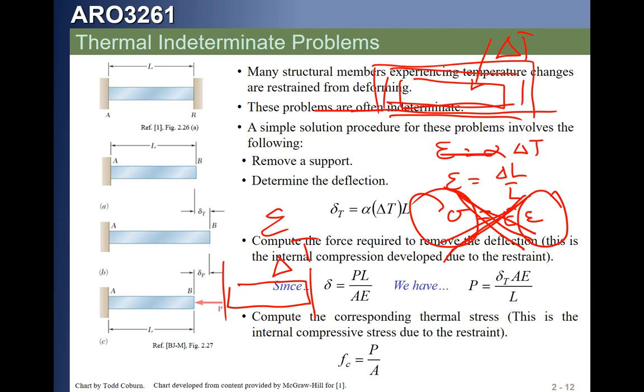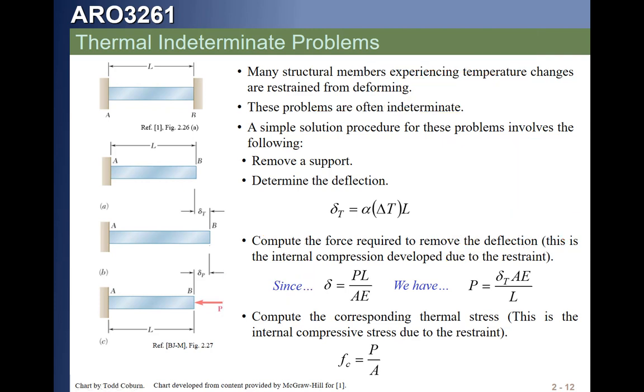Now, when we get to composite materials, we have different materials with different coefficients of thermal expansion. Then the part is trying to do a bunch of different things under the same change in temperature. You can develop a lot of residual stresses due to those thermal effects. It can get rather complicated. We'll teach you all about that if you come back to take composite materials. Got it?